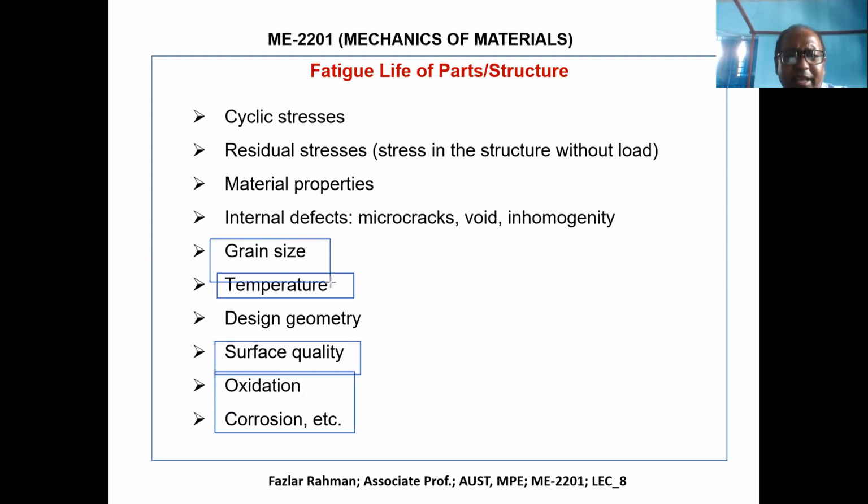Then there is grain size, but forget about grain size, that one is from metallurgy, you don't need to know that much. Then internal defects, say a micro crack or some air bubble inside the material. You use alloy material, but it doesn't mix homogeneously throughout the part. Then it will crack. If the material mixes properly somewhere and improperly elsewhere, what will happen? Cracks will develop from there.